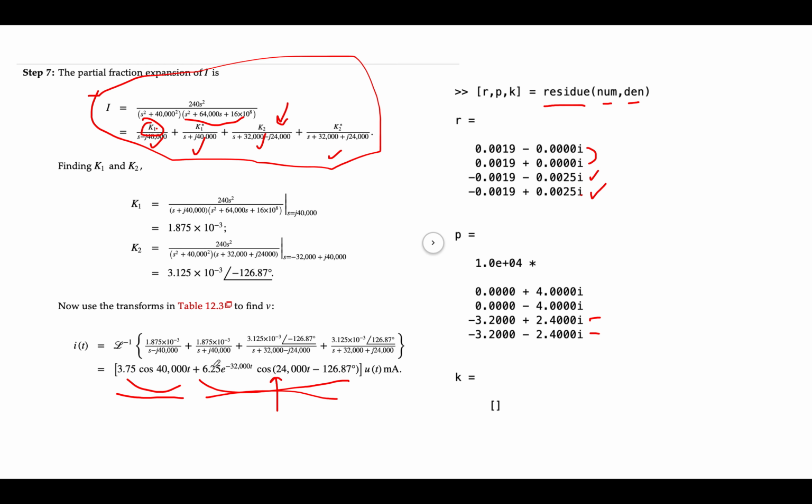So when we do AC circuits, we always just analyze them as phasors, and we neglect the initial conditions or any transient effects of actually turning on the source in the system. So what this problem models, if you do have a sinusoidal source, is this would be what your output would be if you did a phasor type analysis.